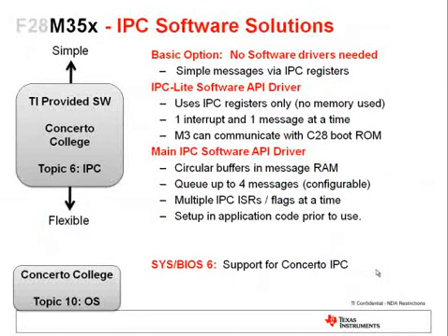So you know that there are 2 cores on this device. You know that they have dedicated memory, and you've heard how I mentioned that having them both on one die eliminates the latency associated with 2-chip solutions. You're probably wondering how they communicate. We've added an interprocessor communication structure, or IPC, on this device. There are 3 ways that you can use the IPC.